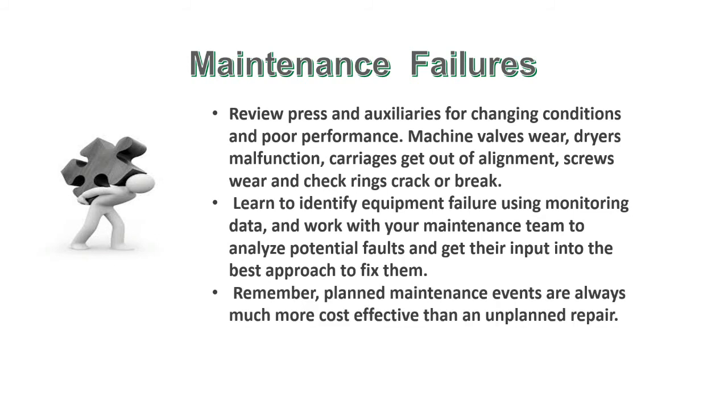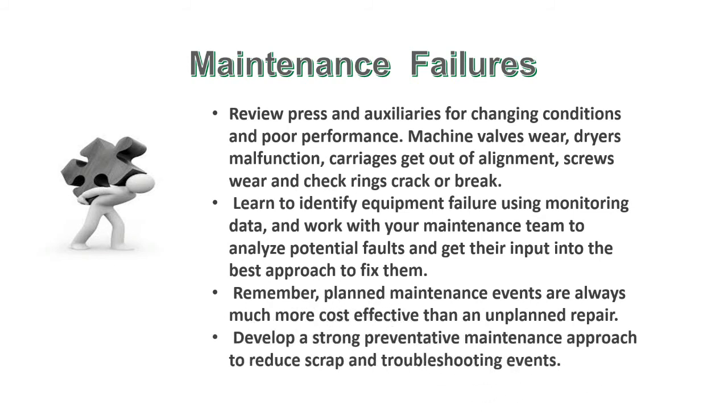Remember, planned maintenance events are always much more cost-effective than an unplanned repair. Develop a strong preventative maintenance approach to reduce scrap and troubleshooting events. Keep a maintenance log. The log can be used to track machine repair, and then the dates from those repairs when they are repeatable. You can use that to establish frequency of when preventative maintenance events should occur.